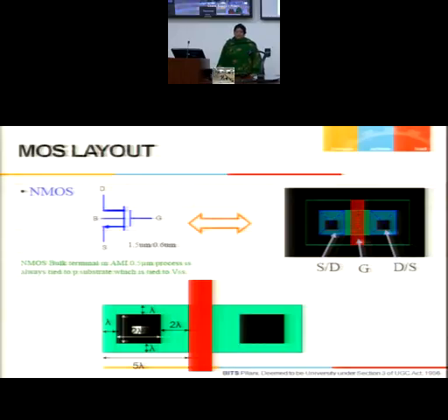Okay. So now, if I compute this value, there would be some parasitic components. Now if I want to reduce it, suppose I do not want a very large capacitive loading. In analog, that means a high time constant, that means a very small pole. You may end up having a small dominant pole. I do not want a very large pole. So I want capacitances to be reduced. So what should I do to reduce its capacitance?